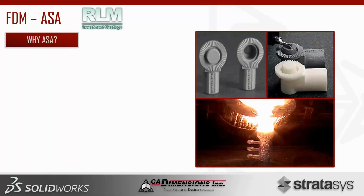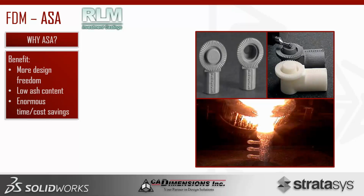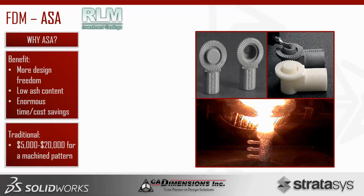As you can imagine, they do investment castings. And now why ASA? The benefits from using ASA are more design freedom, lower ash content, and enormous time and cost savings. Lower ash content meaning because you can sparse out these parts and still retain the outer geometry as opposed to ABS or any thermoplastic, you can get the same results from something like investment casting without having as much wasted product or burnt out plastics collecting within that deposit. So it makes for a cleaner, more efficient investment casting process.